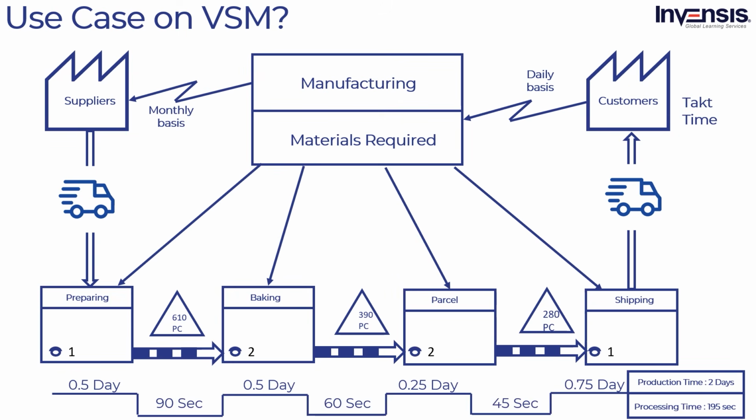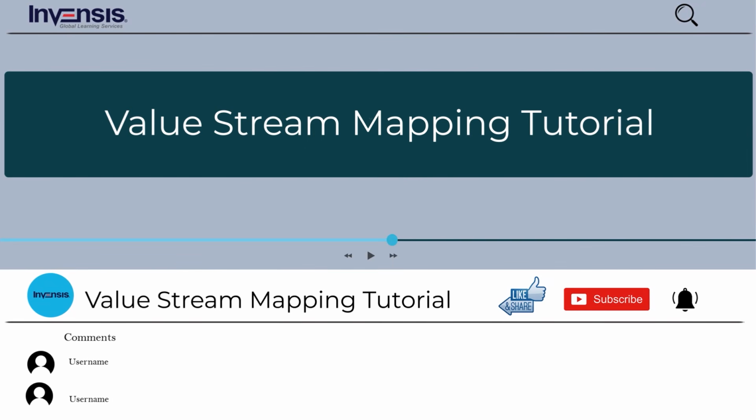In the end, you should create a timeline at the bottom of your value stream map. As value stream maps mainly aim at detecting waste in a process, the timeline is perhaps the most essential piece. At the bottom of the timeline, write down the times for value-added processes taken from the data boxes above. Similarly, on top of that timeline, write down the times for non-value-added processes. Then use appropriate formulas and calculate efficiency. And then accordingly alter your process. Here, we come to an end.